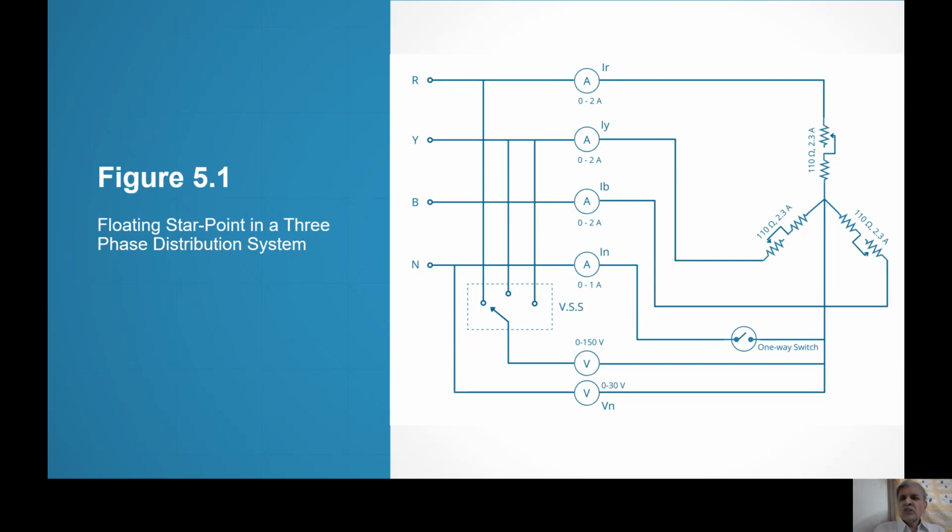Right. Now these 0 to 2 ampere meters and voltmeters you do not have to purchase; they would always be available in any electrical engineering department laboratory. Simple switch is available everywhere. And this 110 ohm, 2.3 ampere rheostat may not be exactly 110 ohm. If you get three rheostats of 185 ohm, that would also be all right. Main point is, all these things are usually available in the laboratory and you can do the experiment at no cost.